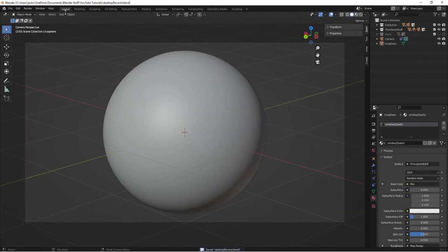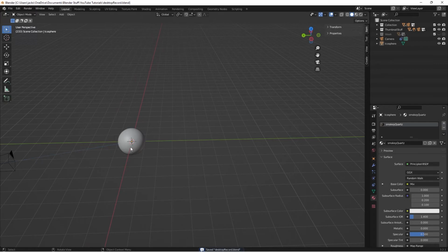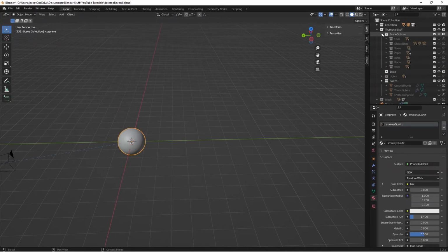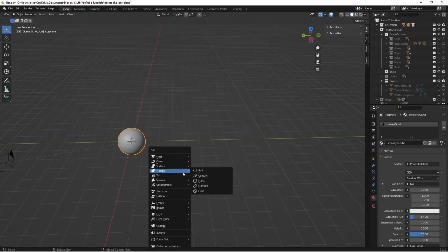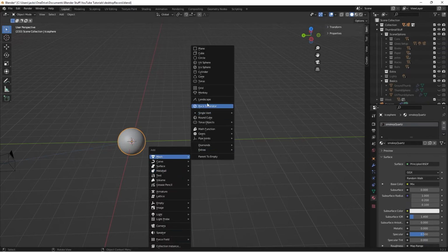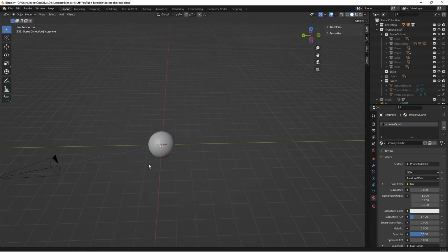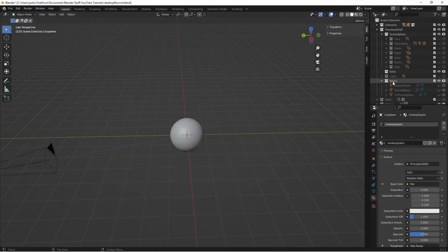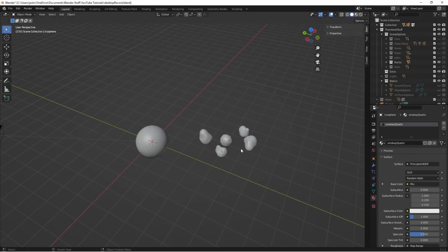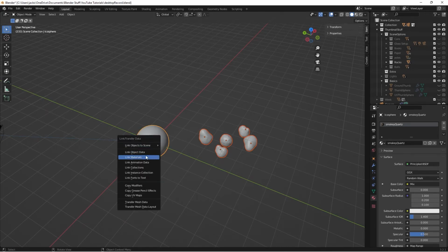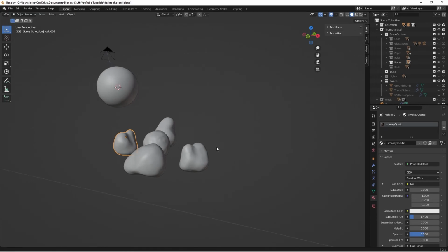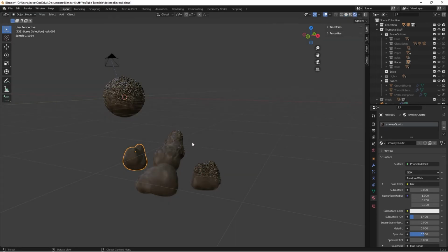So I'll go ahead over to layout, and I'll show you what it's looking like on a rock model. In my thing, I have this stuff set up for thumbnails already. I just used the rock generator. So you can hit Shift-A, mesh, rock generator. And to get that, you just go to edit preferences, search for extra mesh, the extra mesh add-on, and then you can get it there. But anyways, if I enable these rocks real quick, I'll go ahead and select all of them, then select this guy, Control-L, link materials. Now, if I go to rendered preview, just like this,